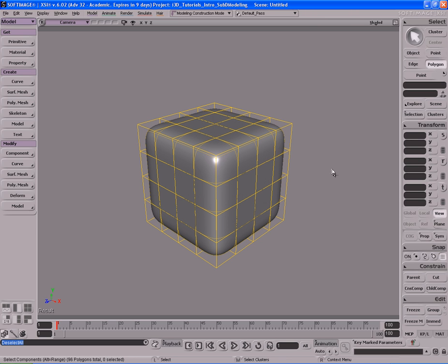I'm going to click out here to deselect all of these polygons that I had selected earlier, and right now we have no polygons selected. When ray casting mode is active, you'll notice there's a small arrow icon underneath my mouse cursor. See, if I switch to regular rectangular selection mode, that little cursor underneath my mouse disappears. When I switch to ray casting mode, you'll see that little triangular icon appear, and that means we're in ray casting mode right now.